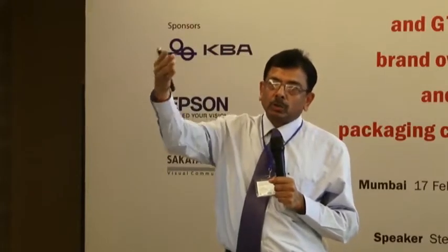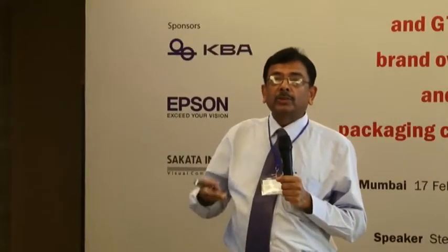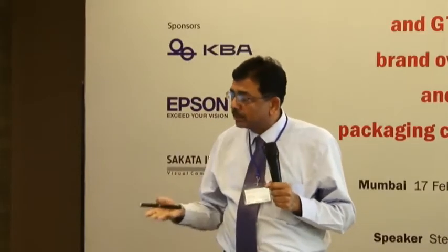Why? When we analyzed, we found that the pearlized BOPP which is used here has a gloss level of about 60 only, whereas the pearlized BOPP which is used in Dubai has a gloss level of 100. So the gloss is more without even OP varnish, and the color becomes very glossy. That's how the substrate also comes into play. If you are laminating some ink with metallized film, the color will change. Somebody had been talking about reverse metallization. It will change because of the effect of the metal. So the color will change.